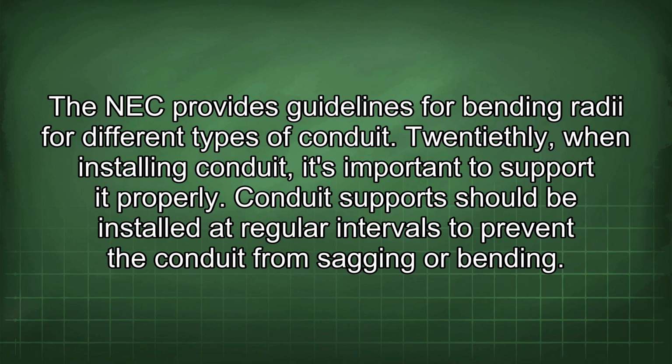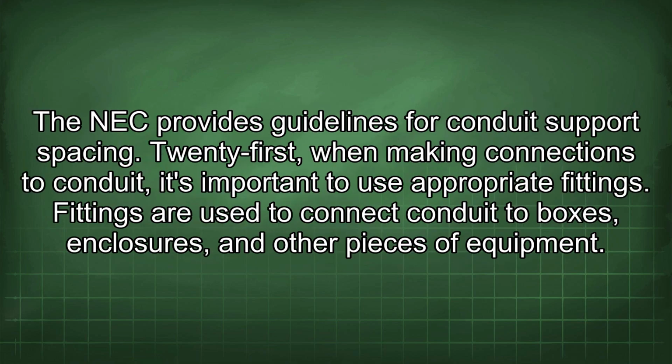20thly, when installing conduit, it's important to support it properly. Conduit support should be installed at regular intervals to prevent the conduit from sagging or bending. The NEC provides guidelines for conduit support spacing.